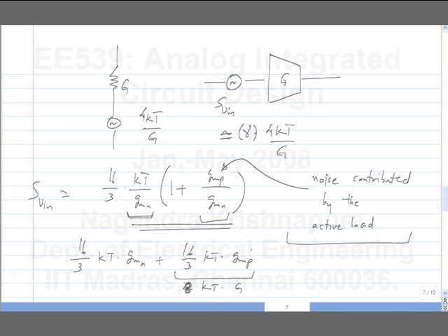But you will need a much higher voltage, right, to do this. The reason we went to active load was because you cannot realize such a high impedance. So that is the bottom line here. We went to active load because we can't realize an impedance equivalent to GDSP with a physical conductance.